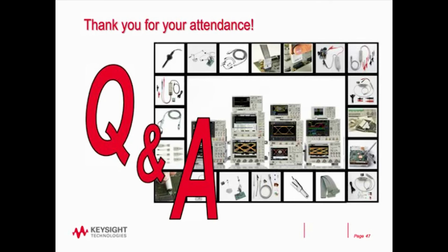The difference in the dynamic range can be huge. When it wakes up, it's measuring a relatively high current. Then it goes back to sleep. There's still activity there. The problem is you can't measure both at the same time. This particular probe has two outputs, one that is high sensitivity, so you can measure down in the tens and hundreds of microamps range, and another output that has a higher current setting.